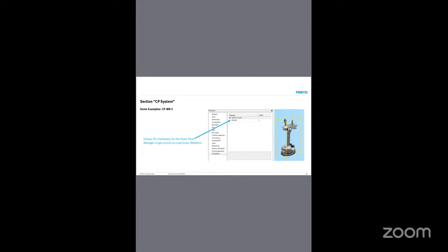So how do we communicate with the fleet manager? We need this ID. Using this ID, the fleet manager communicates. Suppose you have 3 Robotinos with IDs 1, 2, 3. If I say Robotino 2 move to the docking station and send this command, then the Robotino with ID 2 will take this command and move to that particular station.